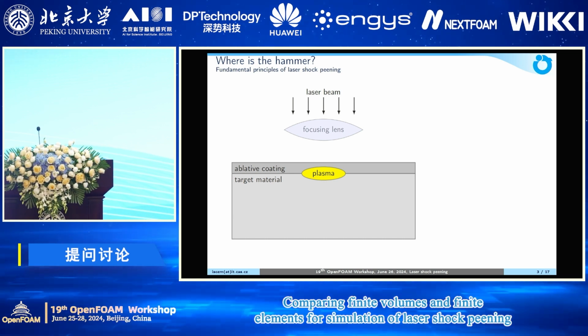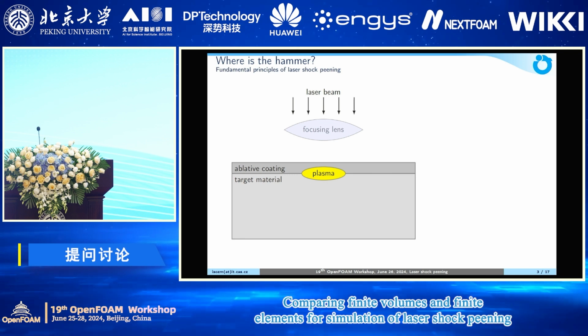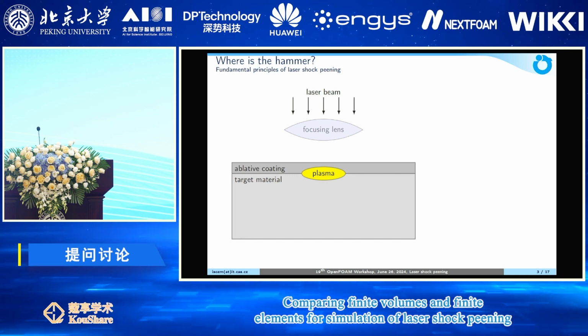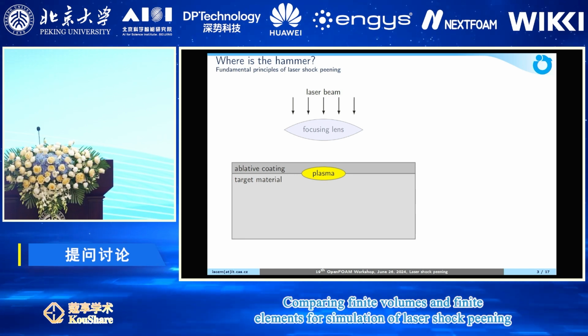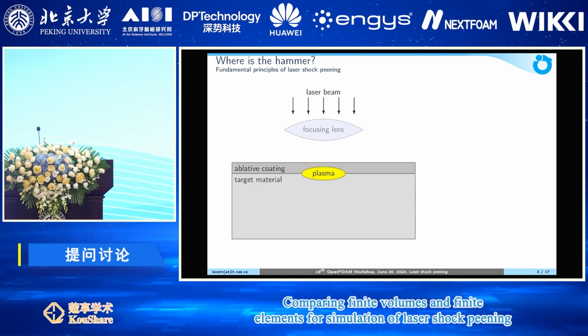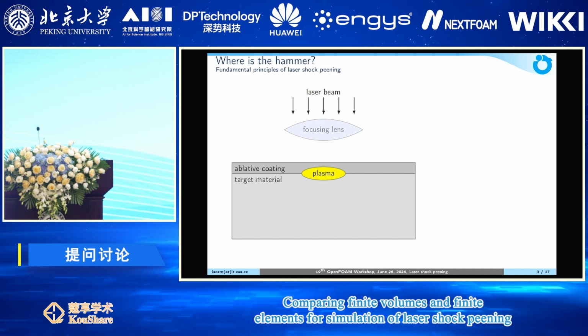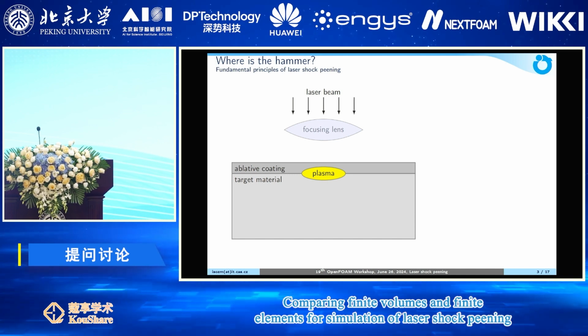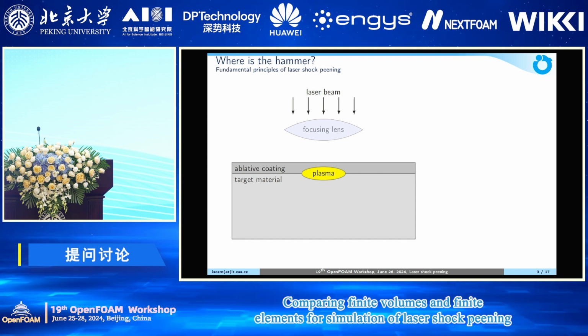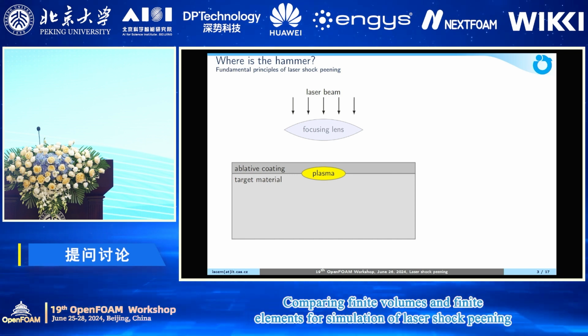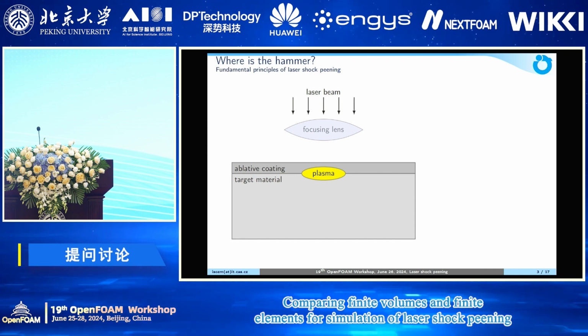The heat effects in there are completely negligible compared to mechanical effects. There has been quite a lot of research done in this area. So we do not need any phase change model, because the phase change is so abrupt. It's the conversion from laser energy to pressure through plasma.